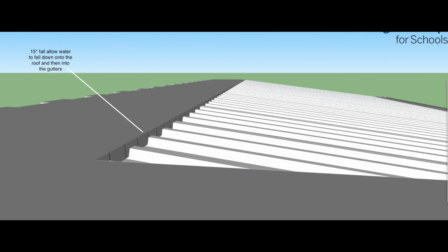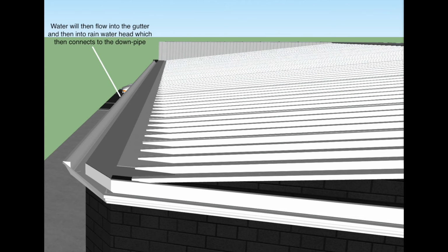A solution to this would be to refine the back end of the panel to have a 15-degree fall, which would just be enough to encourage rainfall retrieval on the roof to the gutters. I would also add guards onto the sides to prevent any leakage. This improvement would allow the building to remain visually appealing and would not detract from the aesthetic of the cafe.